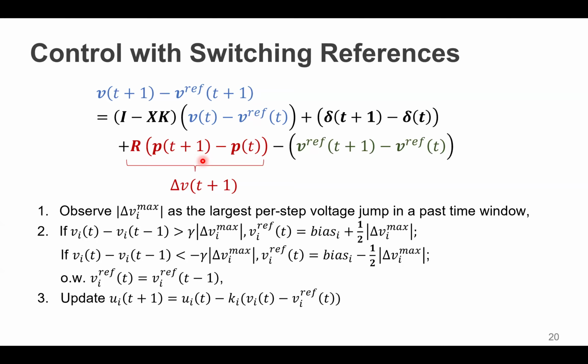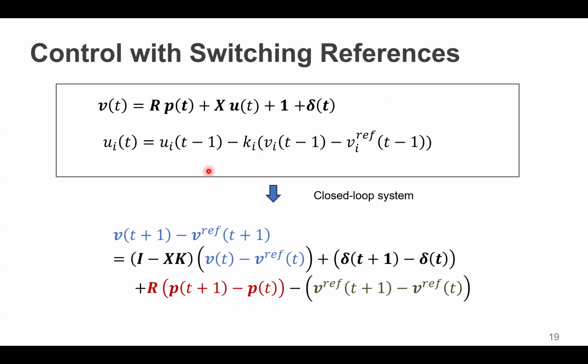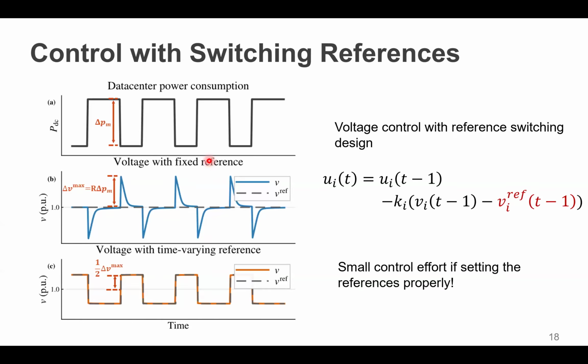Right, so thank you. That's a great point. I should clarify that. Here P(t+1) minus P(t) results in the step voltage change V(t+1), right? Do I know what t+1 is going to be, or is it predicted? It is based on the measurement, done ahead of time. We can do that because of the other assumption that we have a periodic pattern. So after we have seen one period of these voltage fluctuations, you assume stationarity, right?